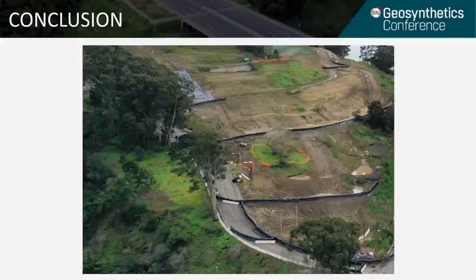To conclude, the use of water-filled barrier walls for stormwater and sediment control on steep slopes was a largely effective BMP strategy for the hillside construction project. The series of 9 barrier wall basins held back large volumes of turbid stormwater and eroded sediment, and also reduced the velocity of stormwater as it made its way down the hillside. When properly anchored, the basins remained stable on slopes of varying steepness and surface type.